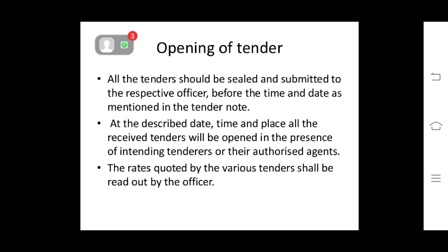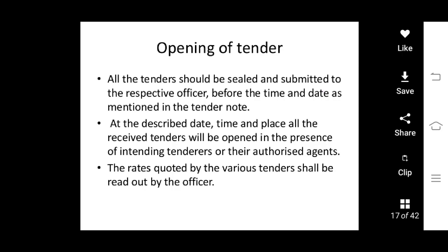Now, we will study the opening procedure for tenders. All the tenders should be sealed and submitted to the respective officer before the time and date as mentioned in the tender notice. At the described date, time, and place, all the received tenders will be opened in the presence of intending tenderers or their authorized agents. The rates quoted by various tenderers shall be read out by the officer.